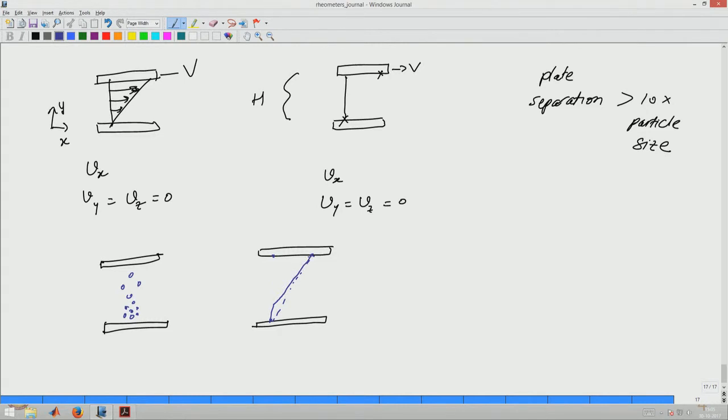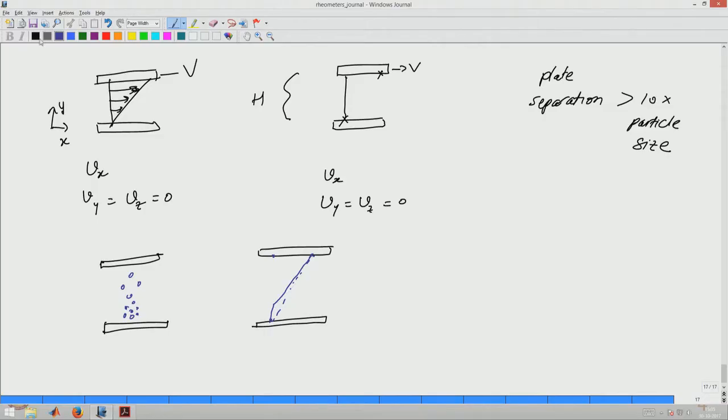increases linearly, right. But the concentration of the suspension will also vary, accordingly we can get parabolic or exponential variation. So what we are saying therefore is we are no longer sure as to what the variation of velocity will be, because the material itself shows certain behavior. When we derived this we assumed material properties to be constant throughout, and so in fact we have this phenomenon called shear banding,